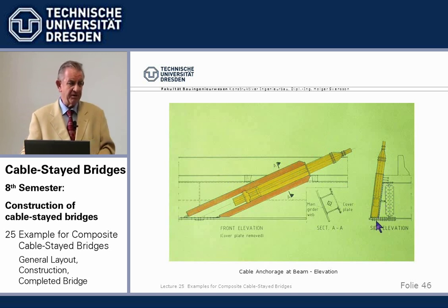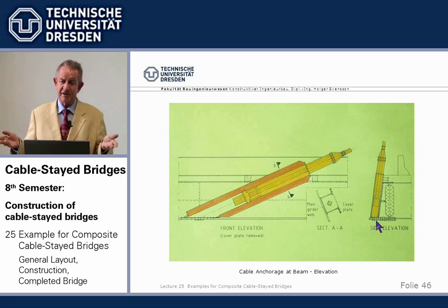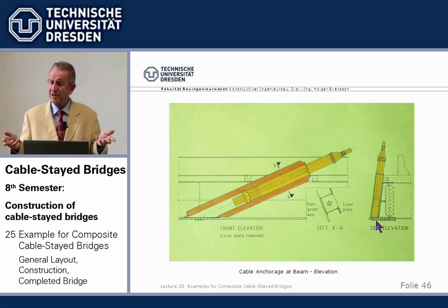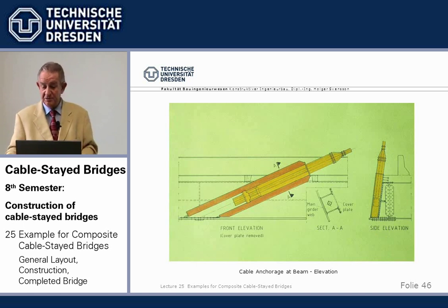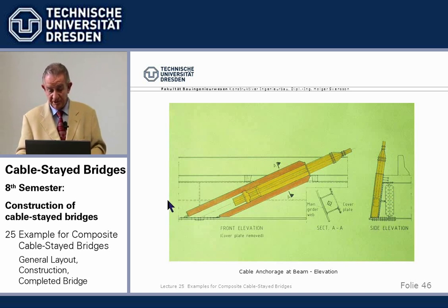The requirement of the Texas Highway Department was they wanted not only the cables exchangeable, but also the cable anchorage, saying something can go wrong. And so we had to bolt that, and then we had to put it on here, and then for stressing here, the bottom flange was in the way for the tension rod, for the tie rod, what I told you.